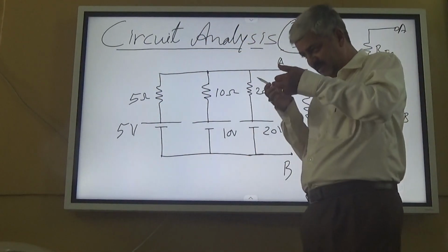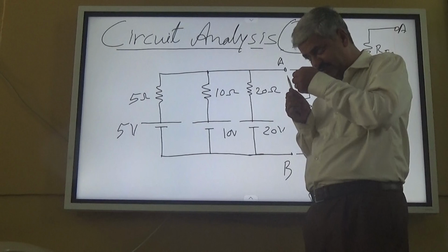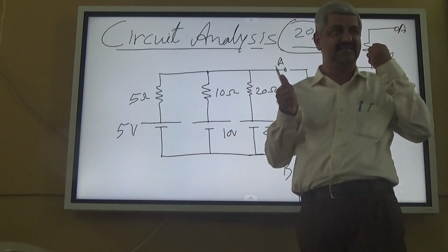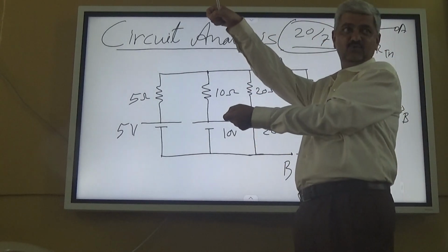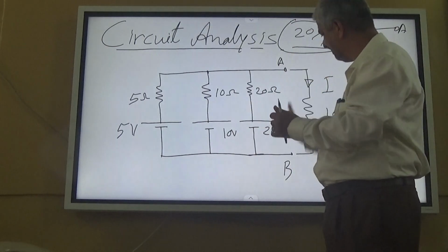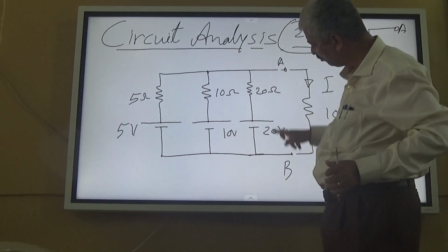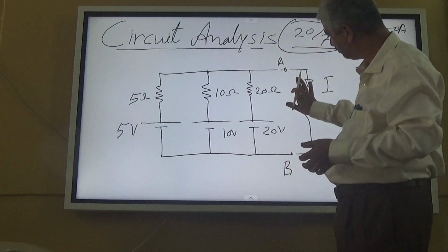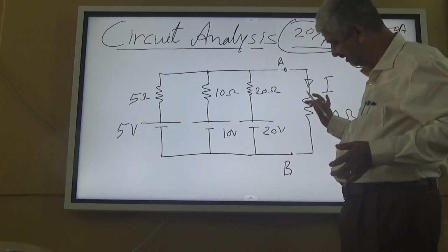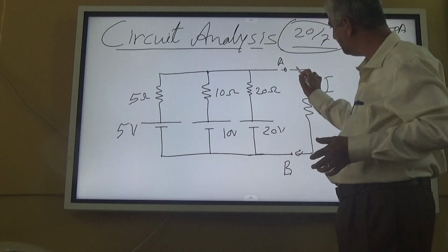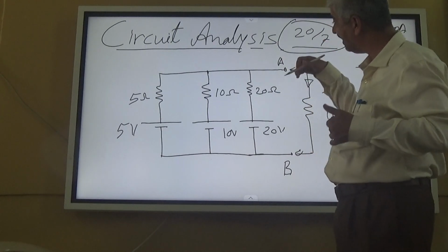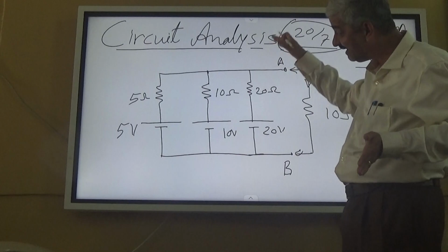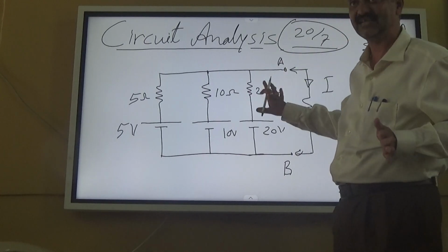When I expect some current to be found in a given resistor, that load I disconnect and call this the open circuit voltage, right? So finding VAB when this is called RL, the load resistance, and is not in the circuit, is the open circuit voltage. So that I have to find out again, and that itself is not an easy task.